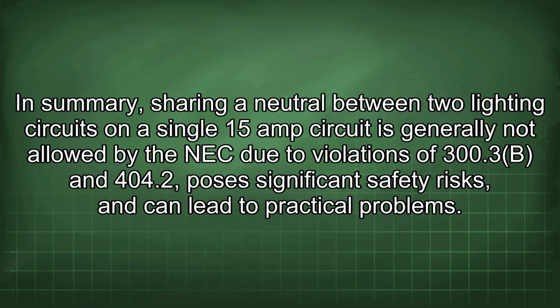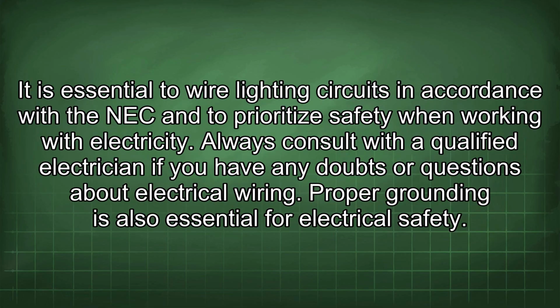In summary, sharing a neutral between two lighting circuits on a single 15 amp circuit is generally not allowed by the NEC due to violations of 300.3(B) and 404.2, poses significant safety risks, and can lead to practical problems. It is essential to wire lighting circuits in accordance with the NEC and to prioritize safety when working with electricity. Always consult with a qualified electrician if you have any doubts or questions about electrical wiring.